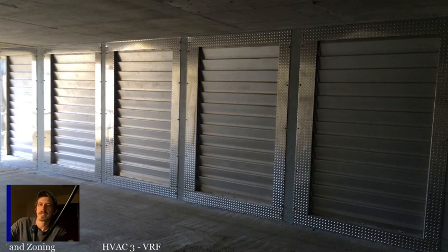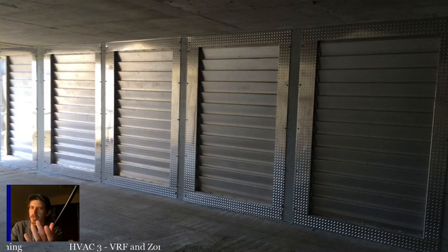So that's why you need that side clearance oftentimes, so you can actually get that blower wheel out, because that blower wheel is a very long, very slender blower wheel. It's got to move all the way out the side, and I've had some like that, where you have to slide the whole thing out in one direction. If you don't have proper clearances on either side, that's going to be difficult, if not impossible, without actually removing the unit. So most of the blower wheels on those ductless indoor units are long, slender, standard centrifugal blower wheels. If you've never seen one, it's basically like a long tube of a squirrel cage.